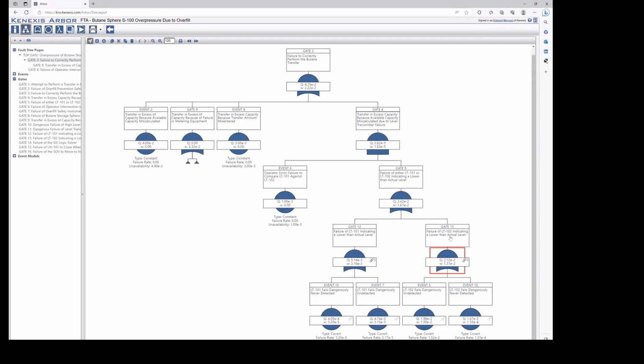The fault tree analysis software knows that it is the same piece of equipment in all those places, and due to minimal cut set analysis, it can elegantly solve for the solution, knowing that the same device is being used in the initiating event, in the operator intervention, and in the SIS.